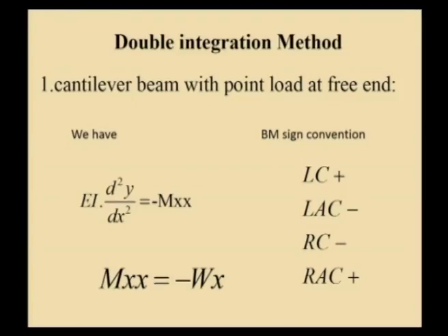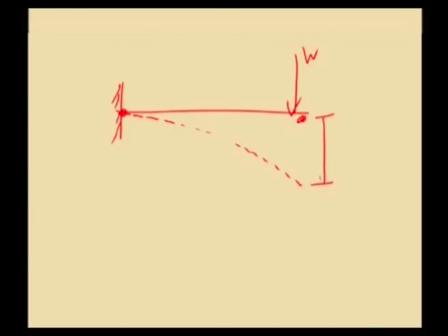So, as we discuss, if you take a beam, either a cantilever beam, and let it be subjected to load like this. We have already studied about supports. So, this is a fixed support. At fixed support there will not be any slope or deflection and the beam will get deflected like this. We call this the deflection curve, and this is one boundary point, this is another boundary point. At the boundary point normally we will be interested in finding the deflection as well as the slope.